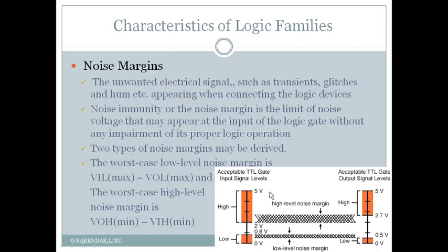So this is a very important characteristic, noise margin, for a digital circuit, which is very useful when you want to make a logic circuit and to know what is the maximum noise that can be tolerated, that occurs actually. Based on the maximum amount of noise that occurs naturally, you design your circuit such that under the worst case also your circuit will function normally.